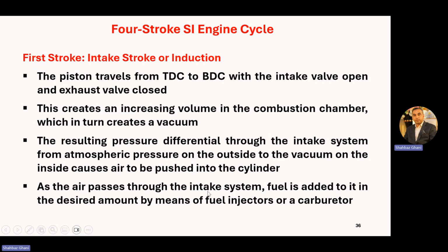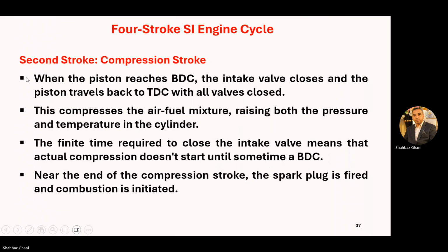As the air passes through the intake system, the fuel is added to it in the desired amount by means of fuel injector or a carburetor. So, second stroke: when the piston reaches BDC, the intake valve closes and the piston travels back to the TDC with all valves closed. So from TDC to BDC, it has covered 180 degrees. Remember this thing: one stroke is equivalent to 180 degrees.